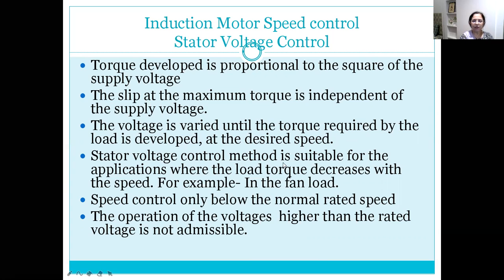The stator voltage control method is suitable mainly for applications where the load torque also reduces with speed, which is typically the case for fan or blower loads.